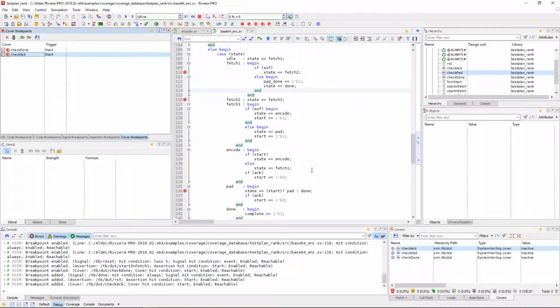When setting breakpoints, there is a case where you can set breakpoints that are unreachable. When a breakpoint is said to be unreachable, it is usually the case that you haven't set settings to generate debug data. There are other situations where a breakpoint is unreachable, such as setting a breakpoint while running a simulation or when the simulator is already in post-simulation debug mode.